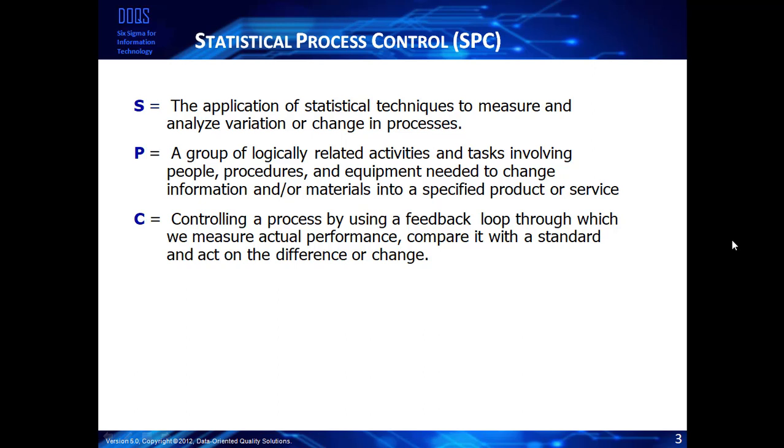And what we're ultimately doing is using a feedback loop to bring statistics back into controlling a process to see if it varies. So does the process behave the same way over time? Whatever variations are in it, are they statistically predictable? And can we use the data to identify when some exceptional case happens that we would want to address as engineers?